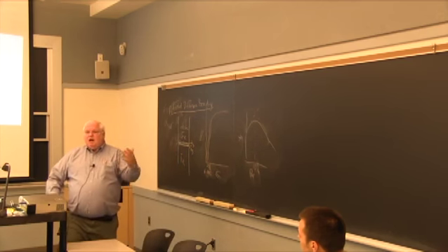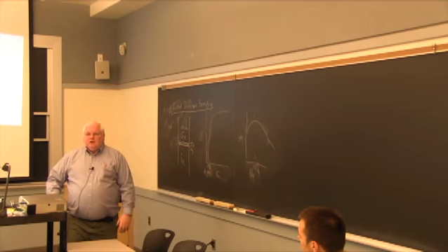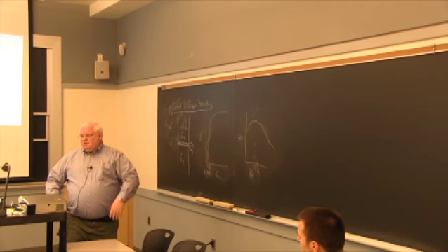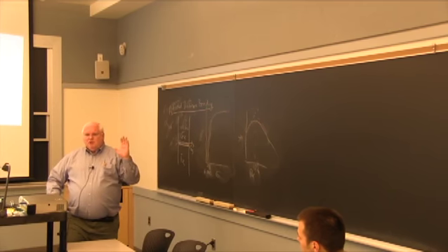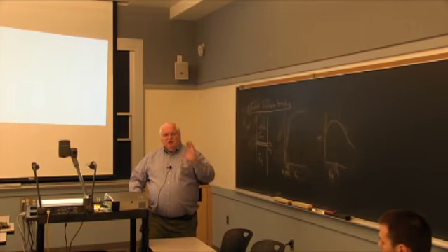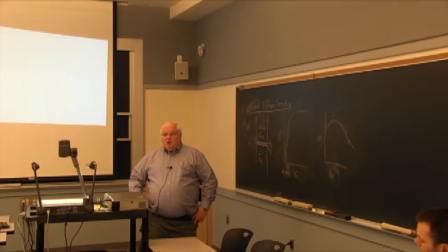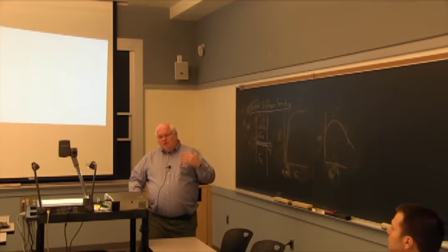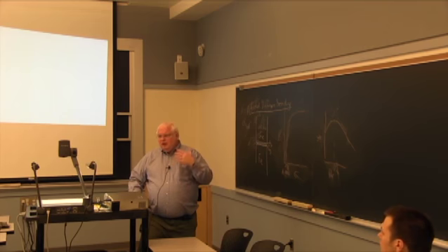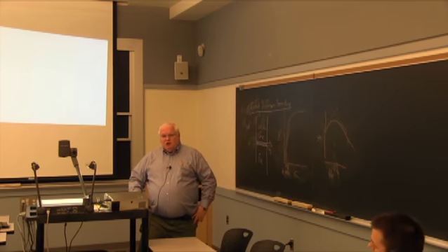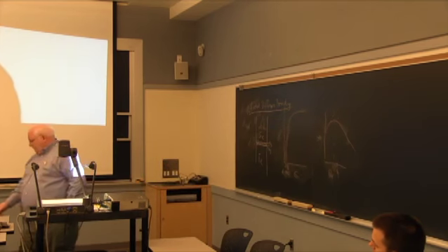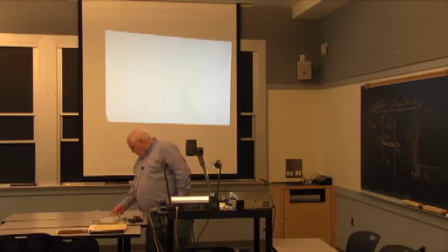And triaxial tension does not lead to shear, okay? If you get into Mohr circles or von Mises cylinders and things like that, you can prove to yourself that a state of triaxial tension or triaxial compression does not contribute to deformation, okay? The material will appear to be much stronger because it's not going to shear. Metals deform by dislocation motion, and you don't move dislocations with triaxial stresses, okay? So you can play little games like that. Okay, that's all I wanted to say about that stuff.